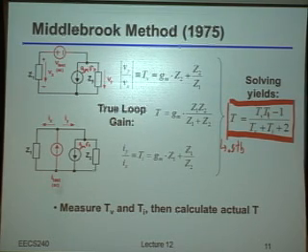But even independent of that, let me ask you guys now, let's say that you had a simulator or you yourself used Middlebrook's method, and you wanted to know whether or not the result you got is trustworthy, meaning that even despite any numerical accuracy issues, you're still getting a pretty reasonable estimate of the final transfer function. What experiment would you try to check if your thing is basically doing okay?